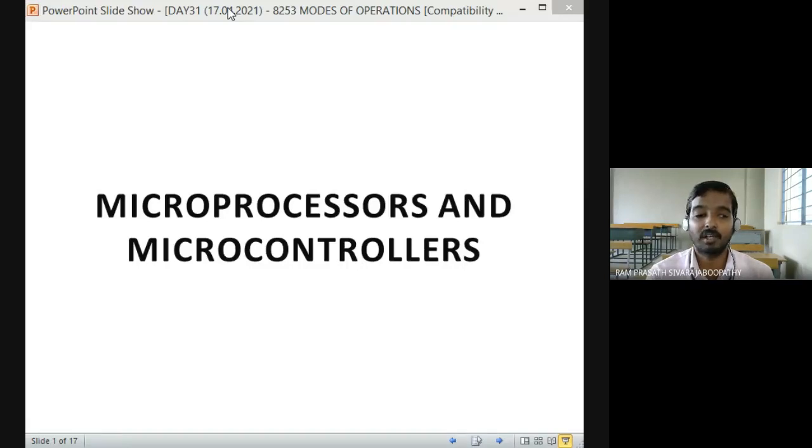We have one output pin, correct? OUT 0, OUT 1, OUT 2, we saw 3 pins, correct? See, these are the counter input and output pins. Fine. Regarding the interfacing portion with your 8085 microprocessor, as with 8255, here we have the data bus, chip select, A1, A0.